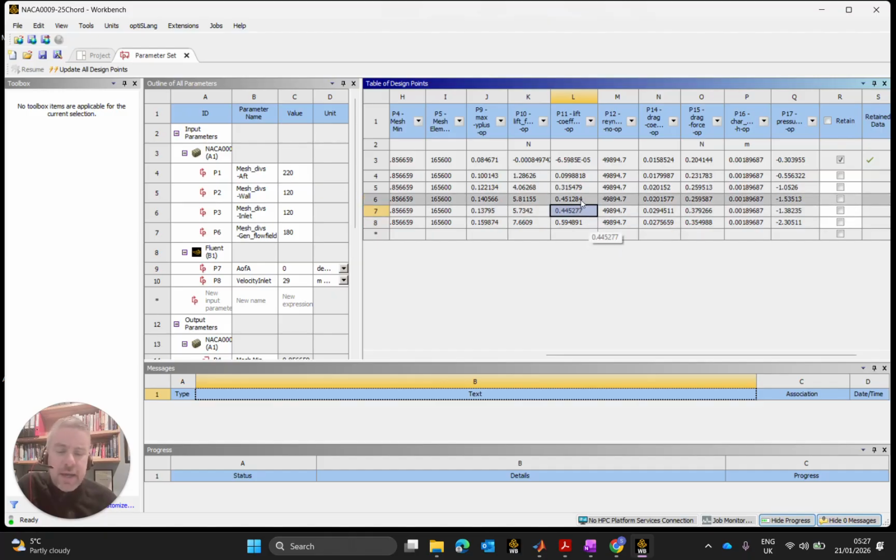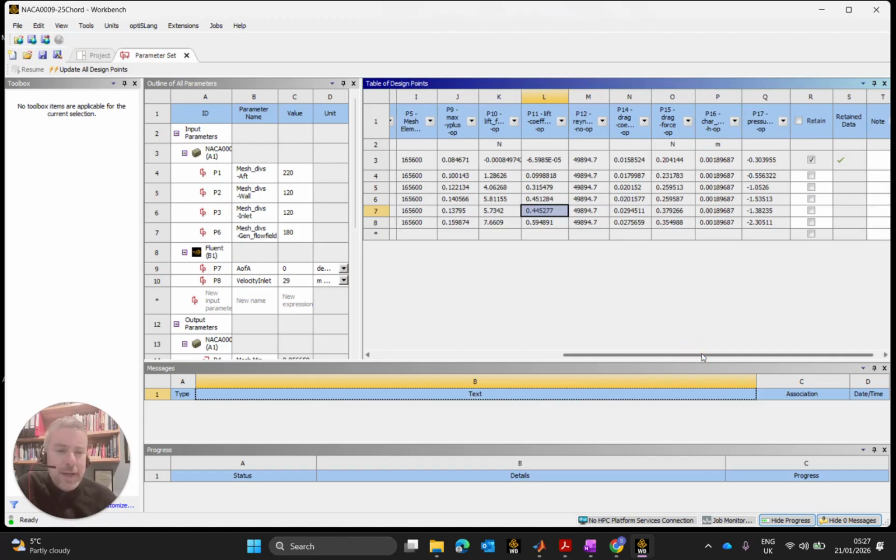However, at the angle of attack of 5, we hit a dip. Our lift coefficients had dropped. Our drag coefficients themselves, our drag forces, went up significantly, just to come back into an apparent trend at an angle of attack of 6 degrees at design point 5. So I did leave the last video saying, check this, check that, maybe it was this, maybe it was that, and it just seems a little bit incomplete to leave you at that.